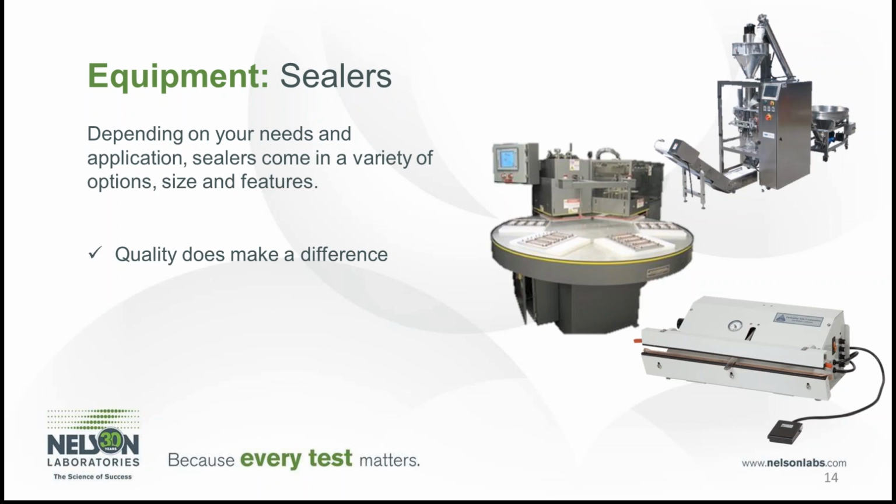The performance qualification is performed on 3 consecutive successful production runs at your nominal setting, and these production runs take into account multiple shifts, different days, changing of tooling if necessary, changing of raw materials, etc., just to make sure that the samples that are coming off the line are to the best they can be.